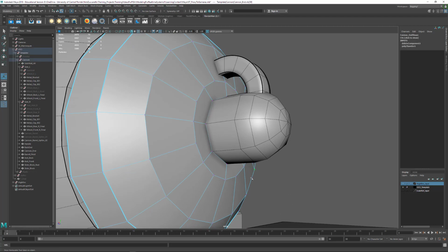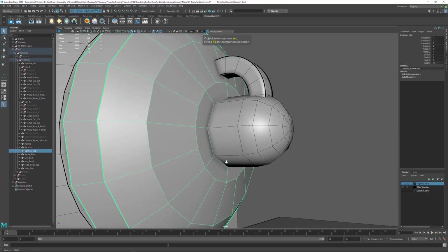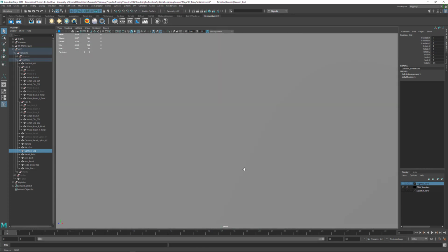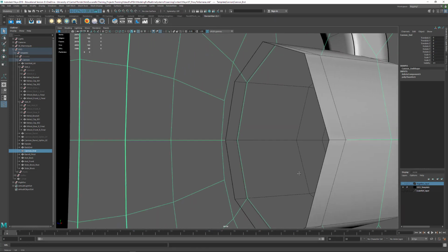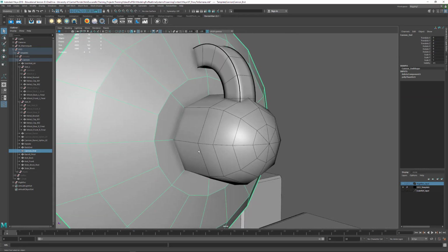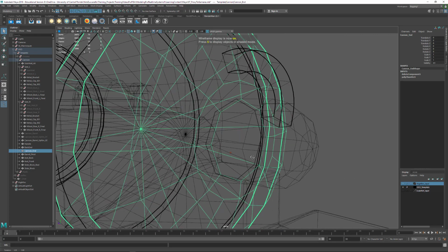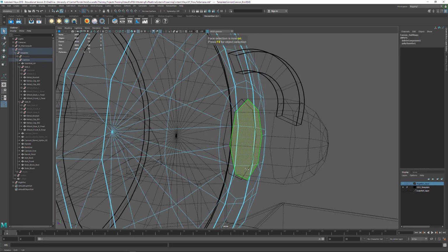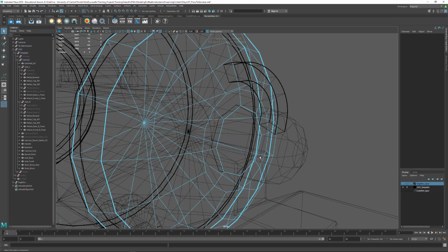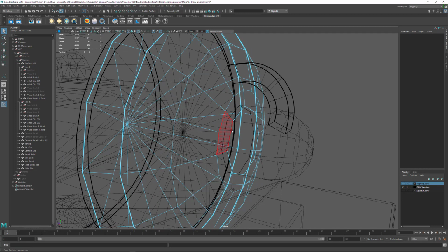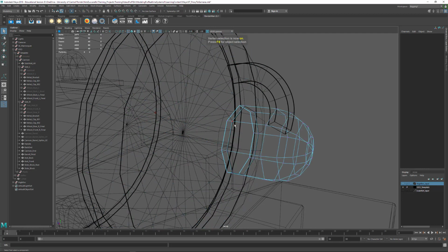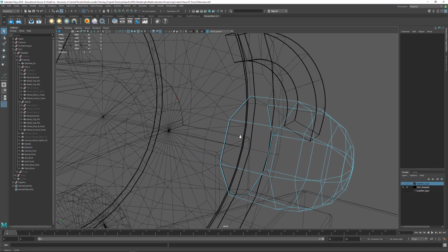Okay, let's tap F8 like that, and if we go on the inside of this, I was going to see if I could fly on the inside of that and look at that. No, let's just tap 4. And if I select this face that we've got here, like that, let's just get rid of it. So we don't need that face anymore. And we don't need the faces on this right here. So I'll hit F10. I'll double click that loop like that and hit Control F11. Select faces, hit backspace, get rid of that. So now we got something that we can start welding together.